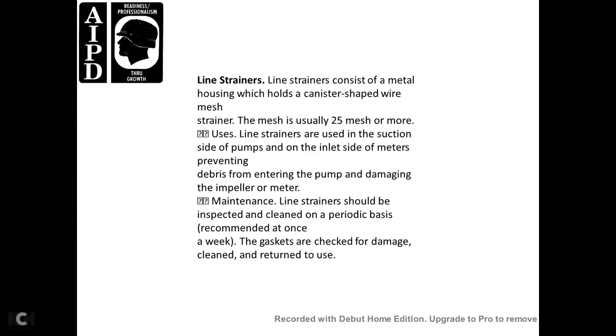For maintenance, the line strainer should be inspected. Cleaning on a periodic basis is recommended, at least once a week. The gaskets are checked for damage, and then cleaned and returned to use.